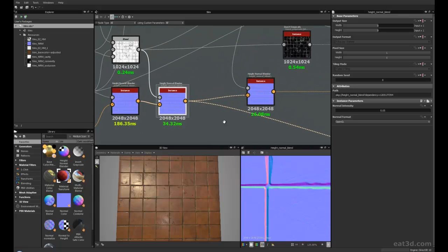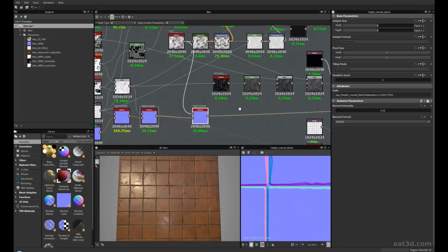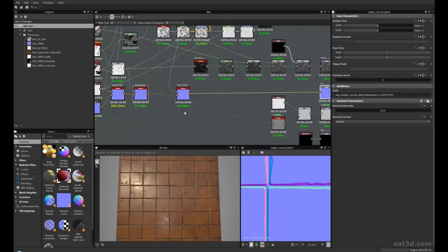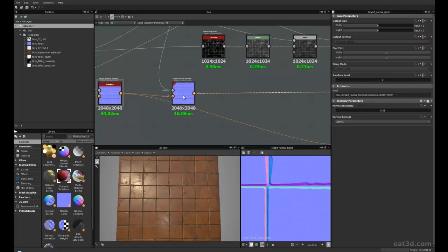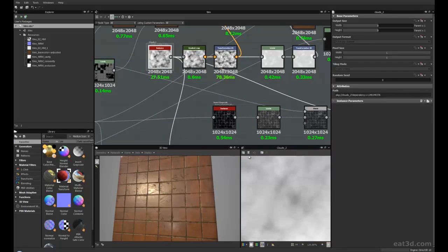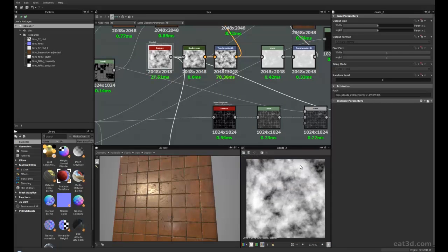So then, what I'm doing from that point is, I'm also adding in another texture, well, noise pattern really, into the height map, into the normal map again. And what this is doing is, now it's pretty hard to see it, but it's coming from this. As you can see, it's just like a black and white cloud, so where it's white, it's going to be kind of sticking up. Just think of them like a height map as well. Think of them as masks and height maps. So this is a height map this time I'm using it for. You don't have to tell it that, but this is what I'm using it for. White, it's going to stick out, black, it's going to go down.